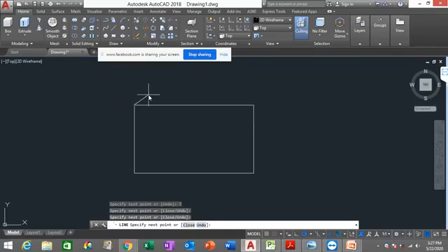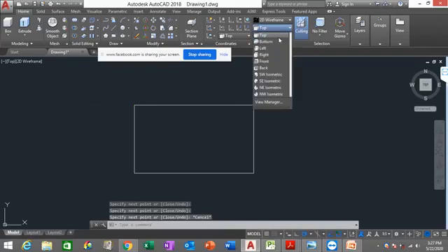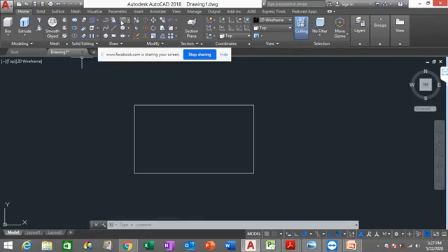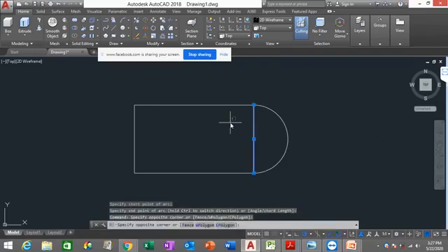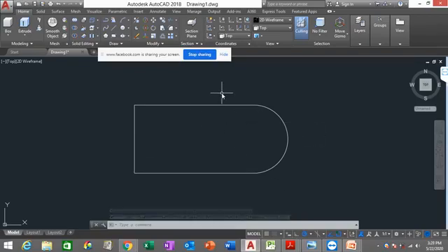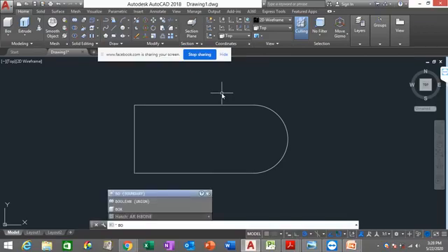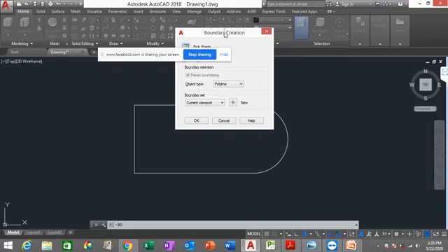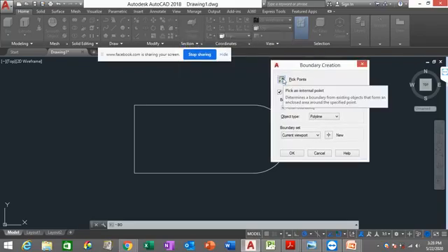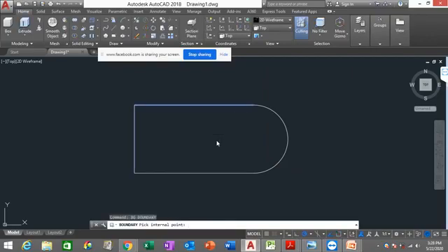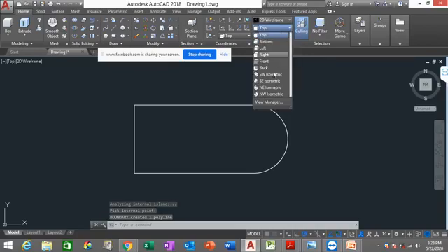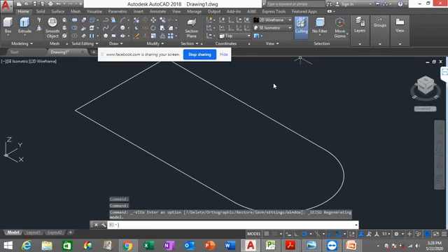Tapi kita draw ni tadi, kita pilih pandangan top tadi. Kita pilih pandangan top. Lepas tu kita akan draw arc. So klik arc kat sini, klik arc, type C enter. Ni center, start, end, select ni, delete. Okay. Then kita kena convertkan drawing ni ke 3D. So dia punya cara dia lah boundary dia dulu. BO enter. Okay. Pick point. In this boundary dialog manager, pick point, click inside the shape here, enter. And then you change your view to SC isometric by clicking here. Alright.